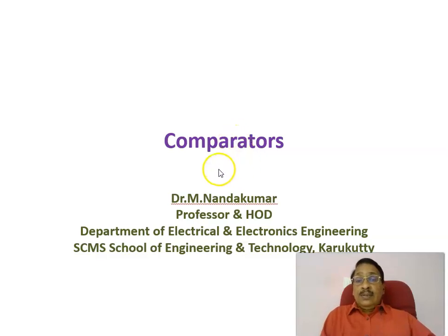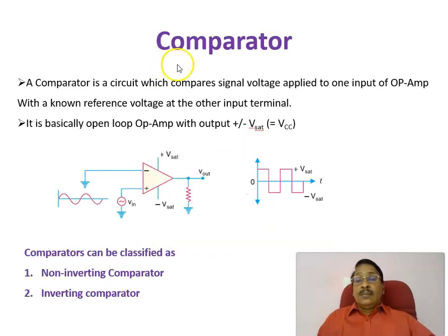In this presentation, I'll be explaining the concept of comparators and a few applications of comparators. A comparator is a circuit which compares the input voltage applied to one input of an op-amp with a known reference voltage at the other input terminal.